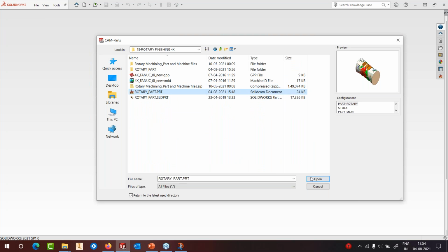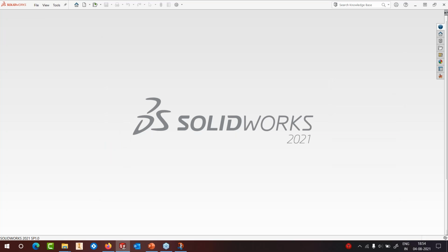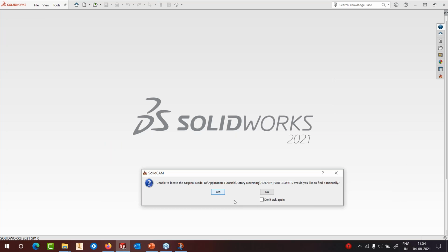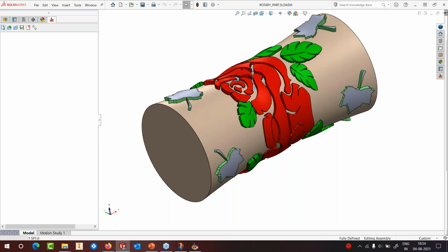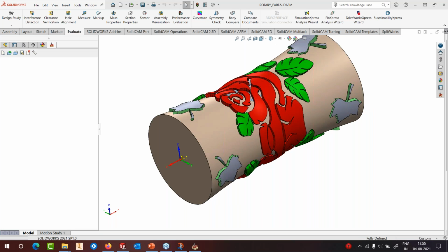Rotary finishing. Like I told you, we also have something called 4-axis rotary finishing. It's generally used when you have cylindrical parts, or indeed they need not be even cylindrical. It could be rotating around a cylinder and look like a cylinder. It could have shapes or anything wrapped around them, like jewelry items, electrodes, round electrodes. So when you get such parts, you can use the rotary finishing.